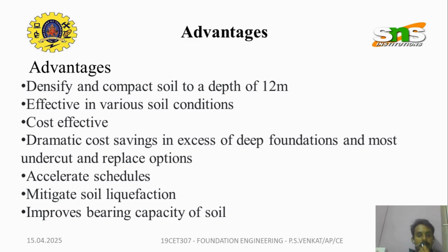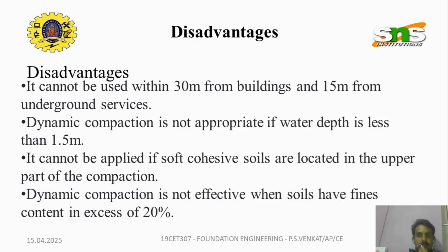It can effectively densify soil up to 12 meters deep, and it is a cost effective solution compared to deep foundations. It accelerates construction schedules. Once the compaction process is complete, the site is ready for quick construction. And also it reduces the risk of liquefaction and improves the bearing capacity of soil.